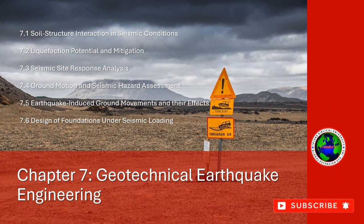1. 1D site response analysis. 1D site response analysis is used to model the behavior of a single vertical column of soil. This approach is commonly applied when the soil profile is relatively simple and can be approximated as a series of horizontal layers. The analysis focuses on the propagation of seismic waves through the layers and evaluates the resulting ground motion at the surface.